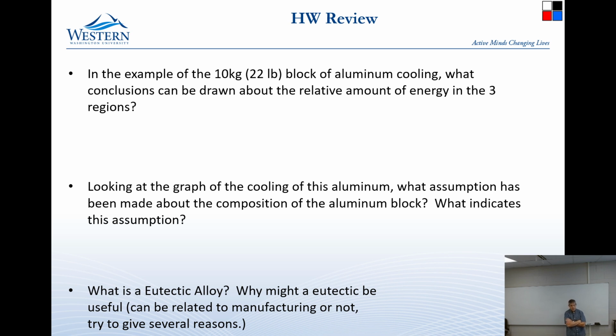Okay, and the conductivity is probably better, or I mean the heat transfer once you start to melt it is probably better because not only do you get heat transfer by conduction but also by convection, so it's going to be rolling around inside. So interesting, yeah. Push a little further, good. We assumed that the specific heat was constant over the temperature range. That's false, but it's close enough to use. It changes with temperature change.